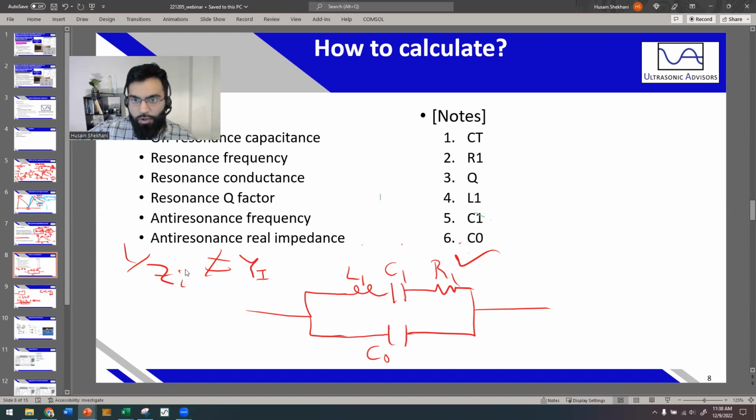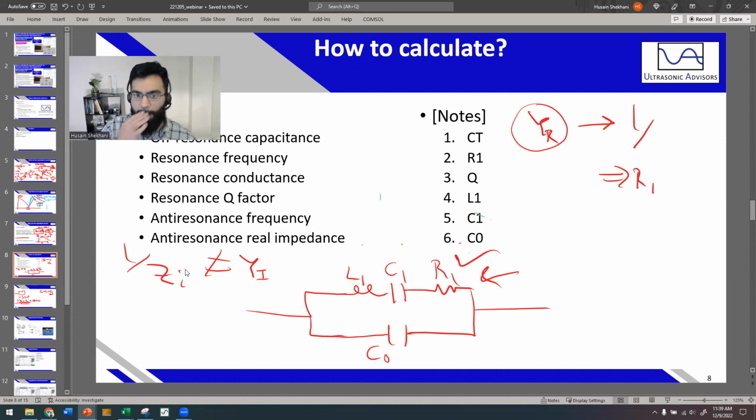However, when you have the real admittance, in this specific case, because the losses are only occurring because of this, you can take the reciprocal and get the resistance that occurs in the LCR branch, because real admittance is never going to be affected by an imaginary contribution from a capacitor. So it's a way to weed out the minimum resistance.